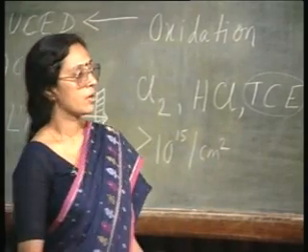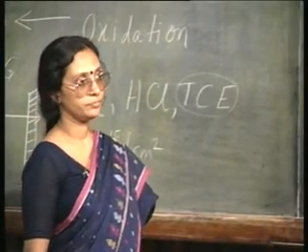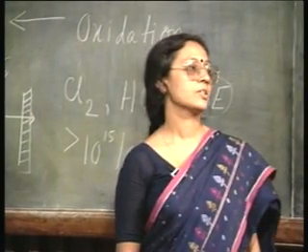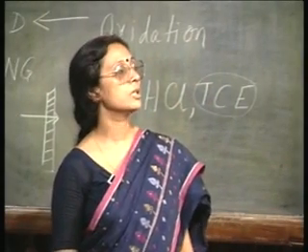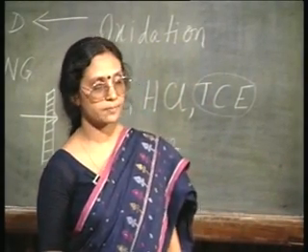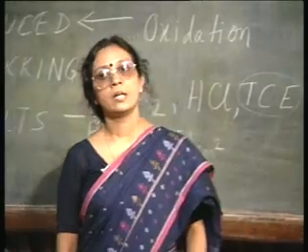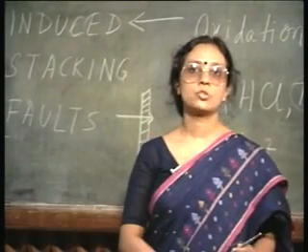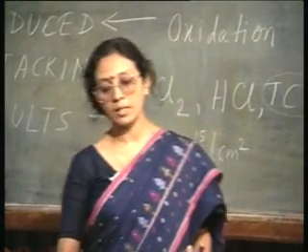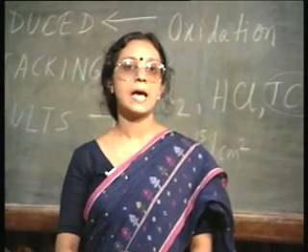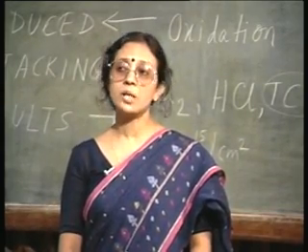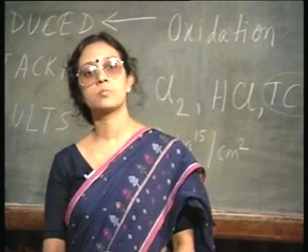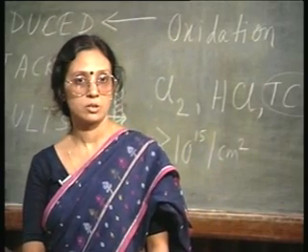So, one first has to understand why the fixed oxide charges come about and then how to reduce the amount of fixed oxide charge. Again, focusing our attention on the actual oxidation process, you remember that oxidation at the interface is taking place at the end. So, what really happens when the oxidation process is over, finished?